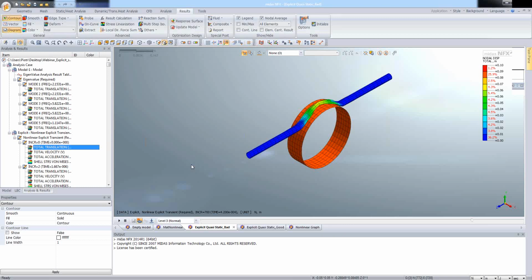The loading rates method will reduce the time scale, so the goal is to model the process in the shortest time period in which the inertia forces will still be insignificant. Okay, so now let's take a look at the example shown on the screen.